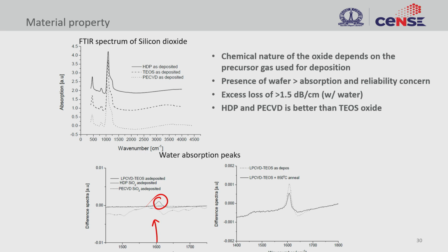So even when you anneal it, right, you have the as deposited film here, and even when you anneal it at high temperature, there is still some water vapor present there. Post anneal, when you cool it down, water, or rather the humidity, can diffuse in, and then it will occupy the space that is available inside this oxide material deposited with LPCVD.